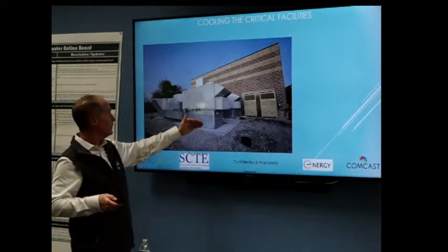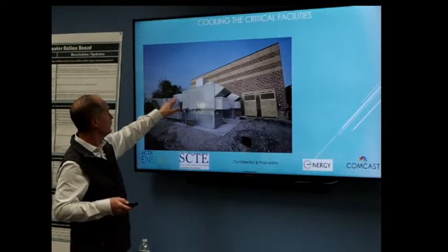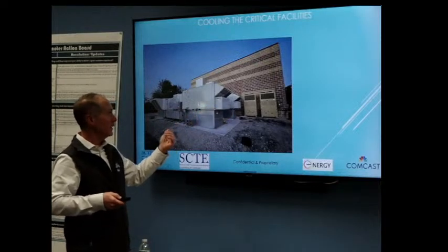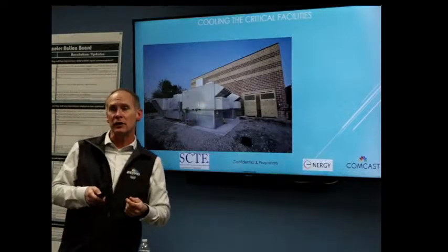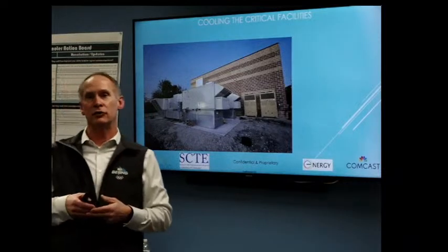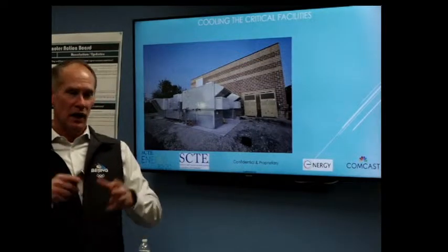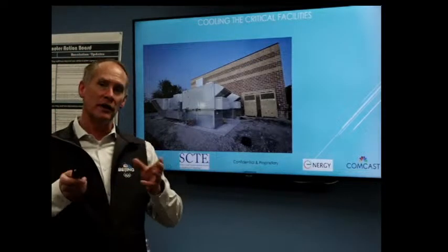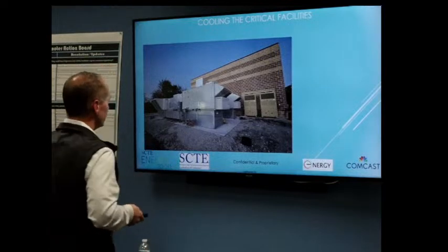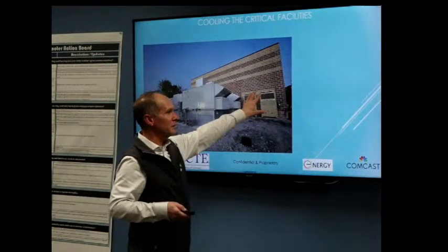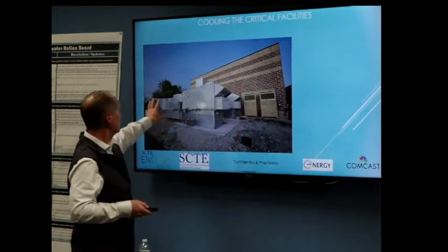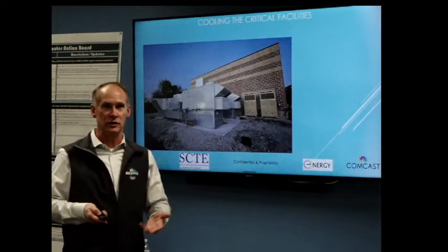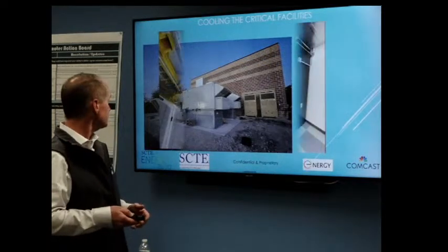You have air coming in through these curbs, going through the ductwork, making its way into the building, and a return is coming out through the building to get back into the mechanical cycle. You have an N+1 or N+2 capacity on your air conditioning. A lot of this stuff is tried and true and is a hybrid solution. It works. You're getting the best of both worlds. You're getting spot cooling where there is a defined load, and you've got flexible ducted cooling that can go through a balancing effort each year as you need to or as you add additional load.